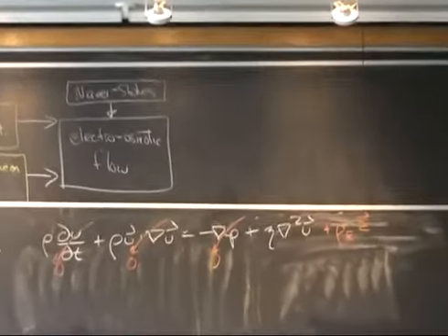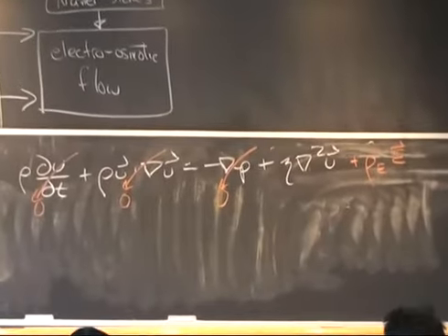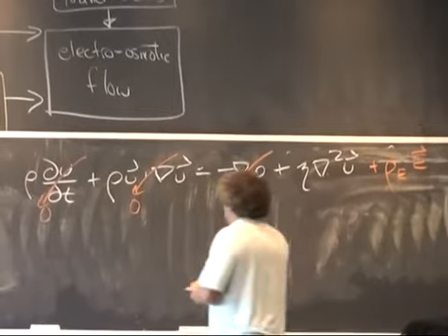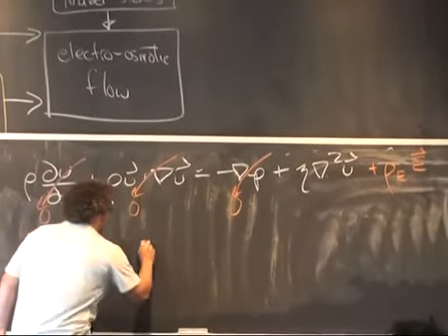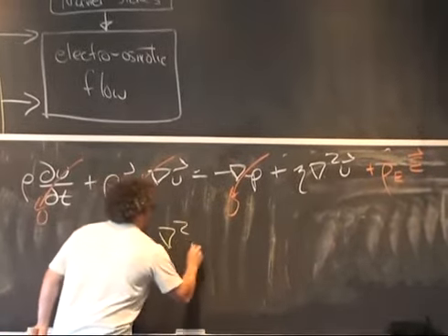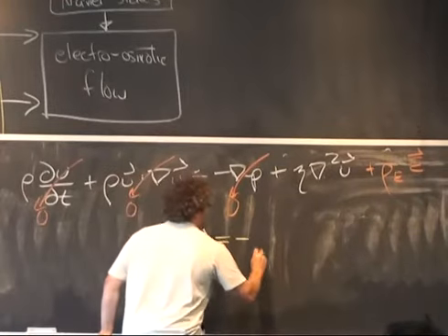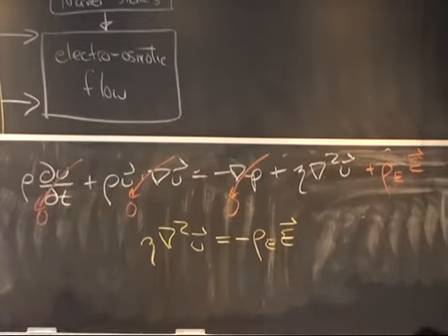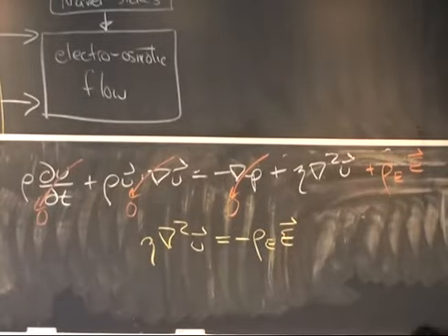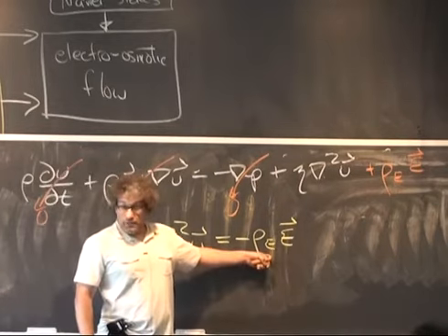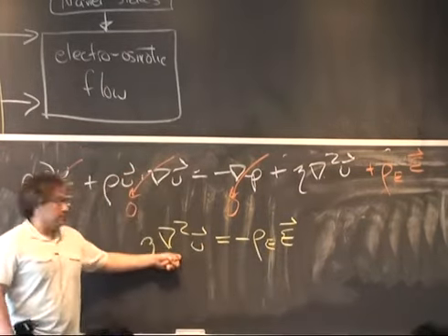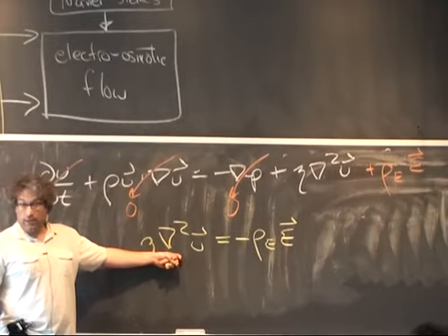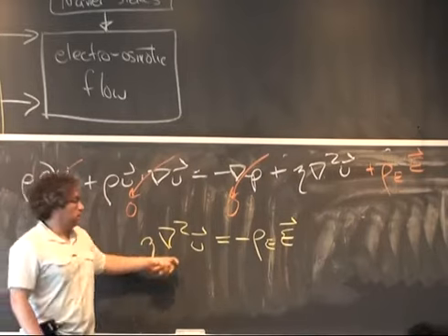And because of that, I now have an extra term on the right-hand side. So now the governing equation I want to solve is given by this expression. Now what I'm saying is that in any local control volume, there's an electric field that's pushing on it, and that's being balanced out by a counteracting net flux of viscous momentum.